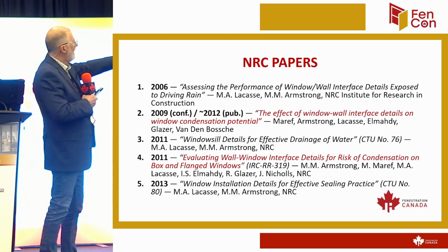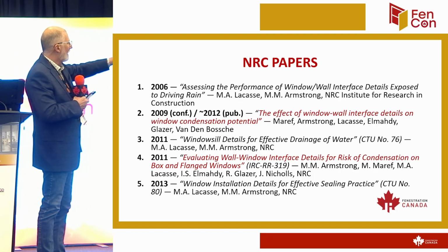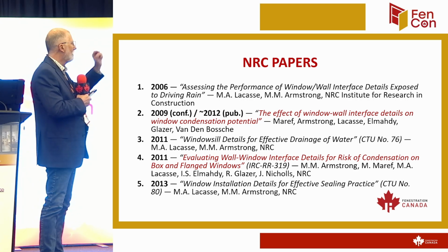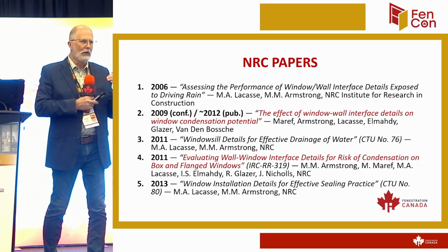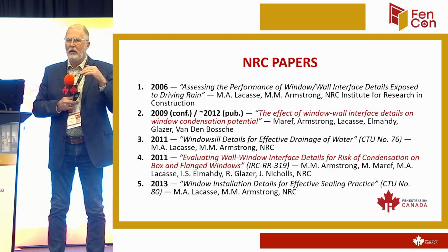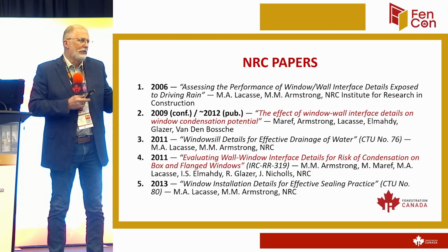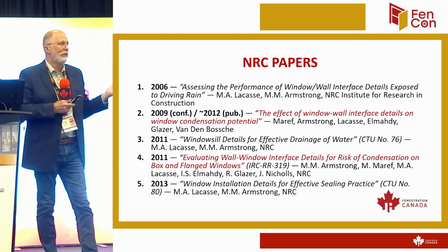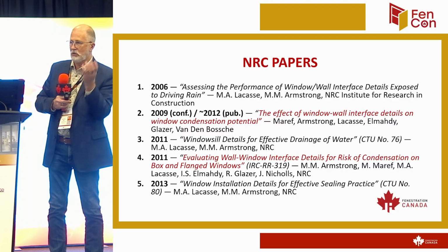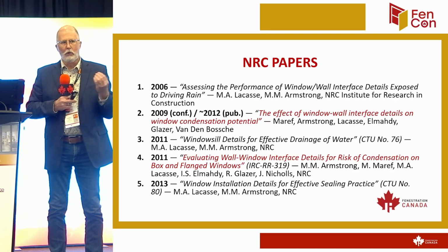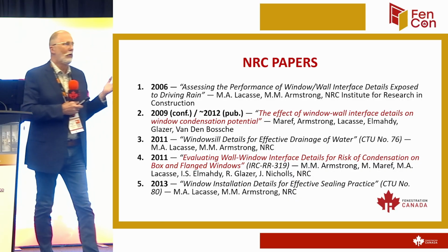So then, in 2009, they talked about it at a conference, and then they published a document in 2012. Well, that just raised all kinds of questions about what happens now if I put that sill pan in and then I spray foam 4 sides of the window, because what's the most common thing we use? It's spray foam. Well, if I spray foam 4 sides of the window and I fill that cavity the majority of the way full, how do I get the water out that could get in there?